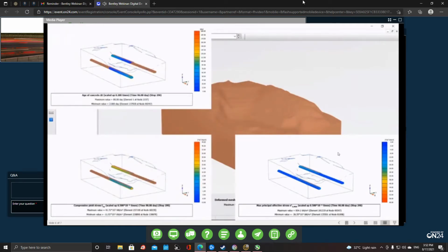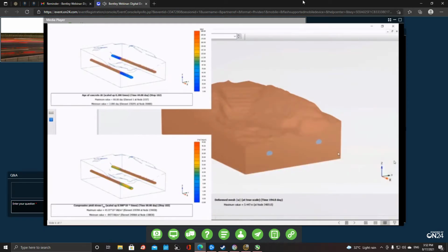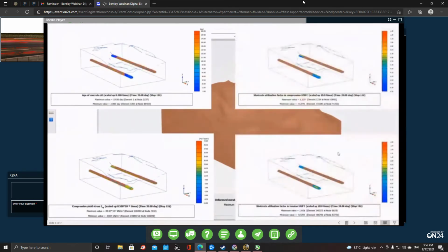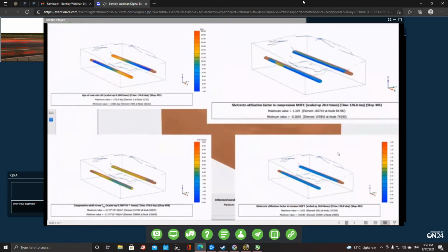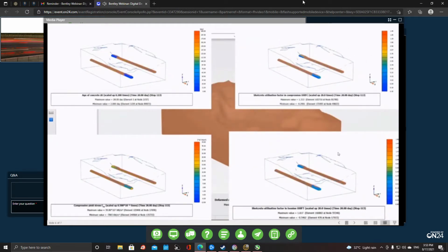These are, for instance, the terrain and subsurface profile, especially along the alignment. In fact, the variation of ground condition as a result of investigation would pretty much set the tone for the tunnel alignment. In general, we want to avoid existing underground infrastructures like foundations, basements, and utilities. It becomes increasingly difficult to achieve though, in the already congested urban cities.